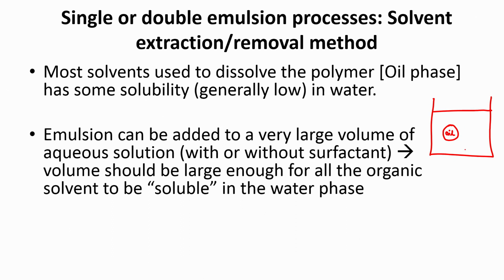and then of course there is some shaking going on. So, it is continuously moving around, but the evaporation can only happen from the surface. But the surface here is water. So, for this oil to evaporate, there has to be some oil present on the surface, right. And for that to happen, the oil will have some solubility in water. Let us say the solubility is very low, only about 0.001 milligram per ml of water,